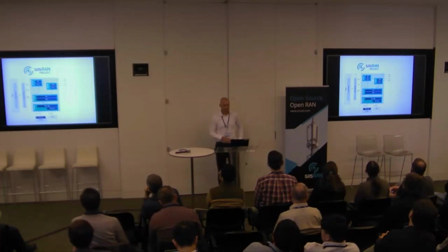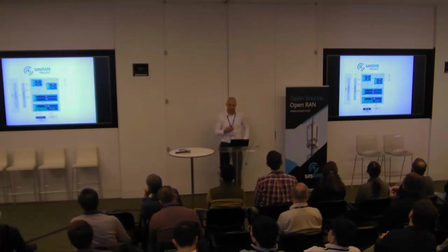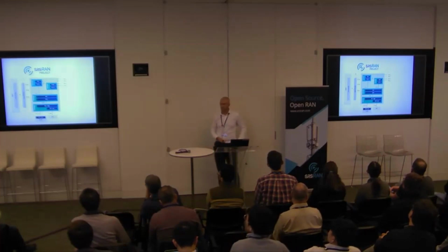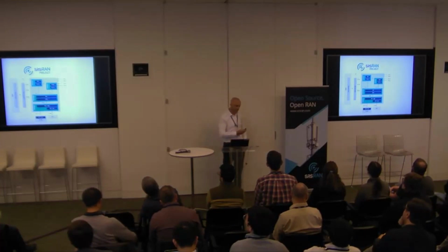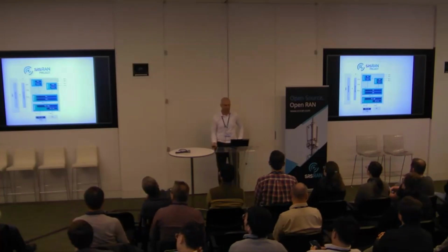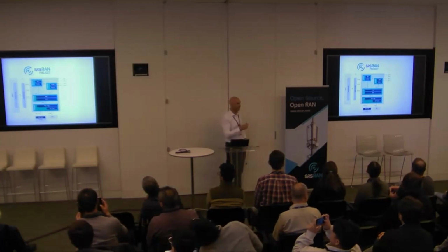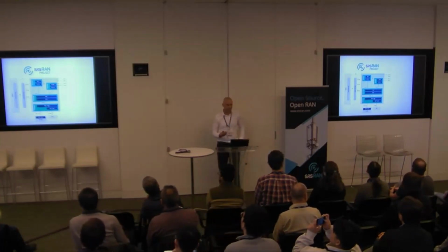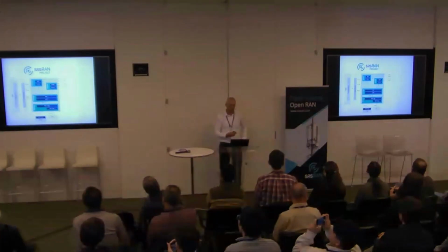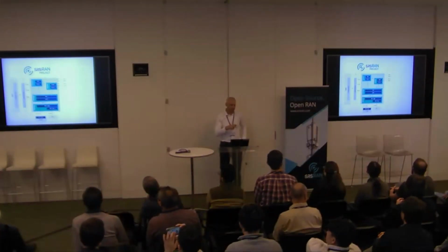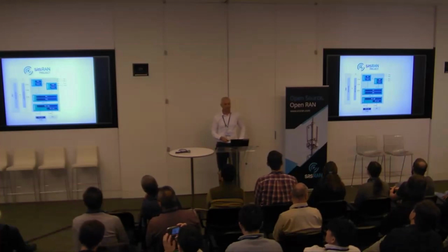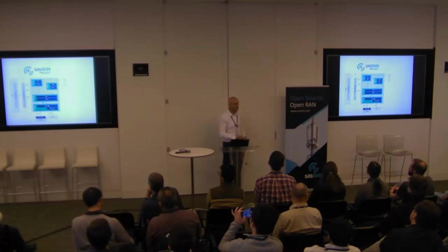And when I talk about designing for scale, it's designing for a massive real world deployment. So we want this to be the default for anyone that's building RAN use cases. We want to build for flexibility. So it has to be self-contained and standalone, but it has to be easily adapted. So we're building in split 8 plus split 7.2 on the fronthaul. We're implementing our own fronthaul library. We're providing a CU DU fast path for deploying the CU and DU together on the one machine. We're adding optional support for hardware accelerators. We're adding optional SoC support with a FAPI interface built in from the outset.